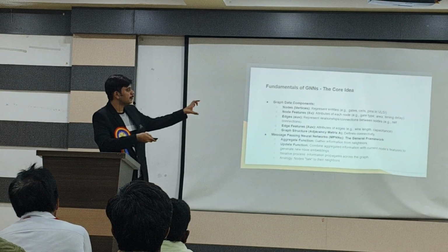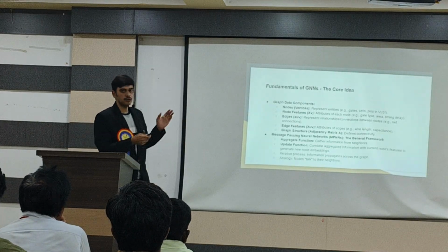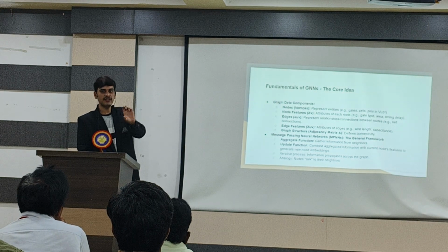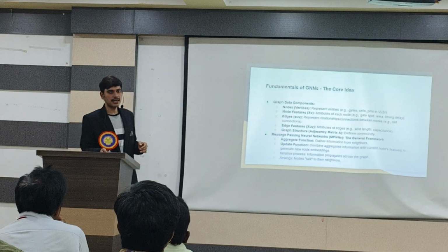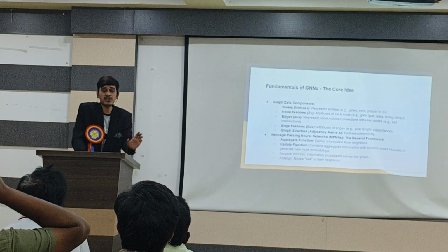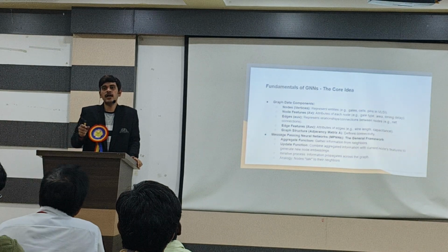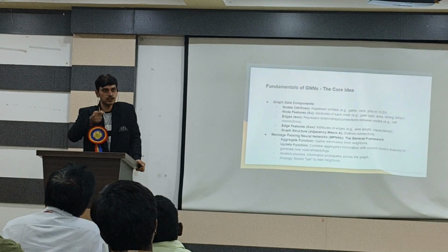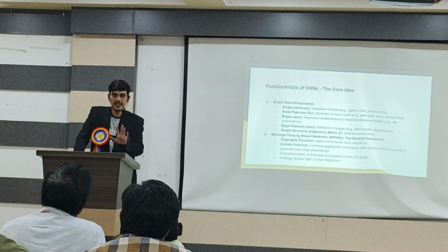So here the nodes are gates, cells and pins. Node features include gate type and area. If a gate is a node, it has a node feature, and that is stored in a vector. This node has a gate type, like P type and N type, and the timing delay and area, how much area every gate has. Only then can we know how much chip area we are going to fabricate. Because we have D2, D4, D8, these are the drive strengths used for the different gates.